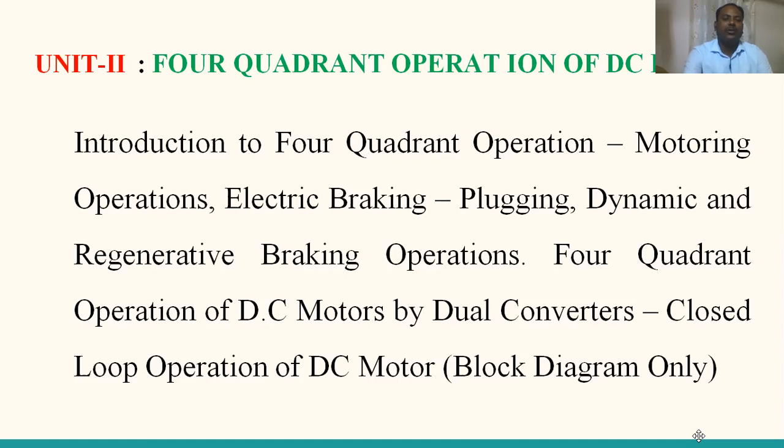So in four quadrant operation, we particularly concentrate on the motoring as well as the braking operations, and also four quadrant operation of DC motors by dual converters. One converter gives two modes of operation, that is motoring and braking, and another converter provides the remaining motoring and braking modes.